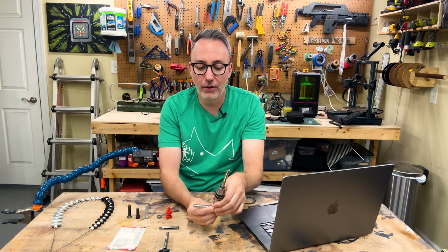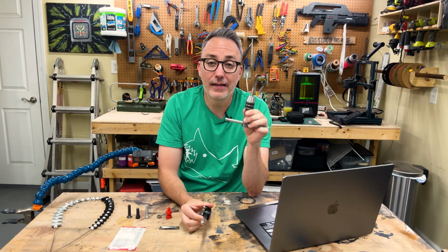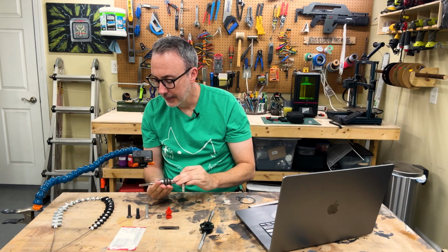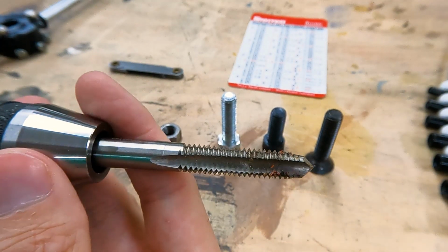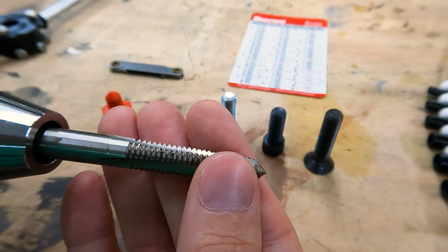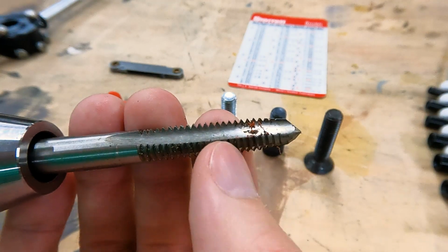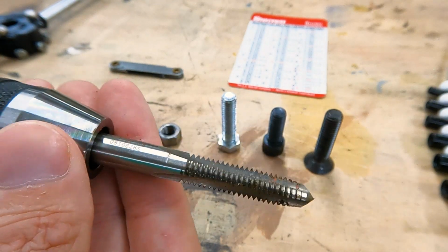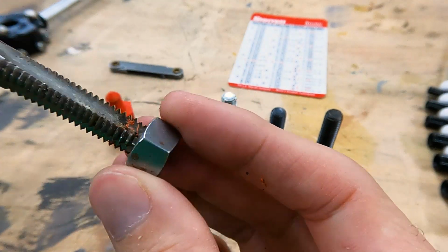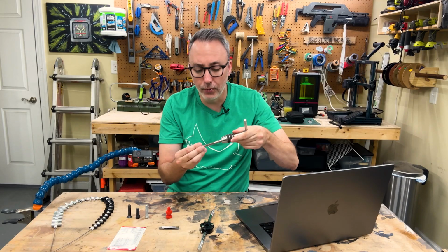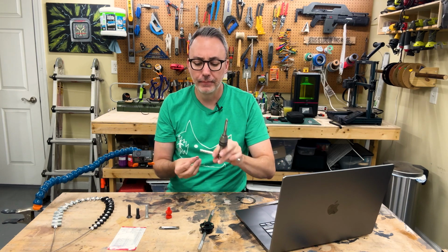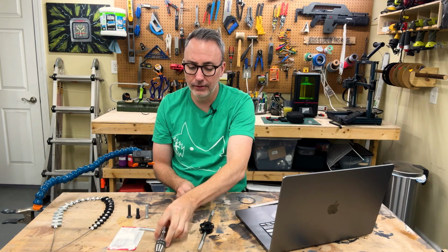But the two things that I want to point out are a tap and a die. So a tap looks like this. Essentially, you would drill a hole that's a little undersized, and then you would turn this by hand, and that would cut grooves, it would cut your threads into that hole. So this is for internal threads, like if you were to cut the threads inside this nut. To cut threads, you really have to twist and be careful not to break your tap, and you want to use cutting fluid and things like that. So that's how you would cut internal threads.